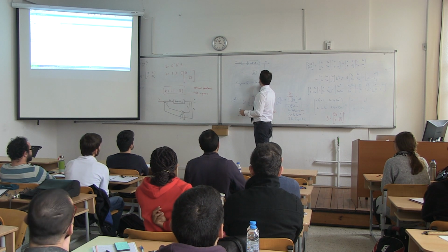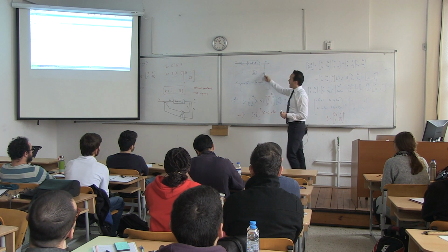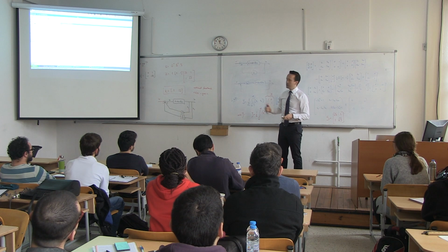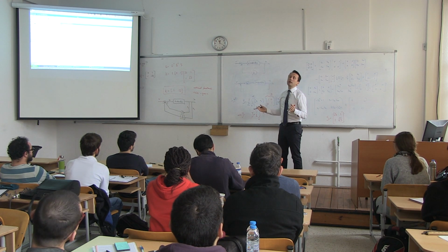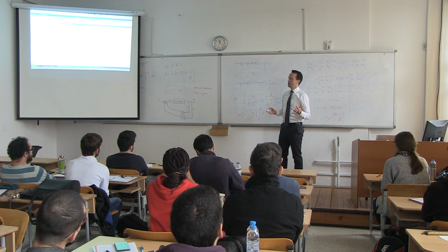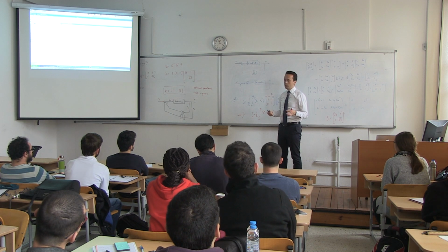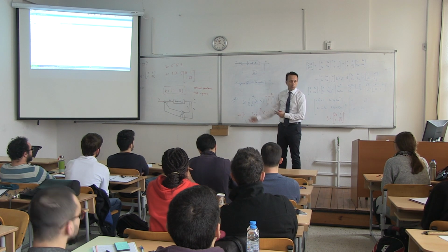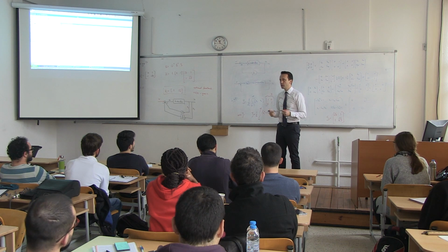Plus Bu, x. These two architectures, the calculation of k is the same, right? Remember that. Because the system matrix for both cases is still A minus BK. So putting the k over here or here doesn't really change the problem. So in other words, if you want to find this k, it is still the LQR problem. It's the same way you calculate this k.